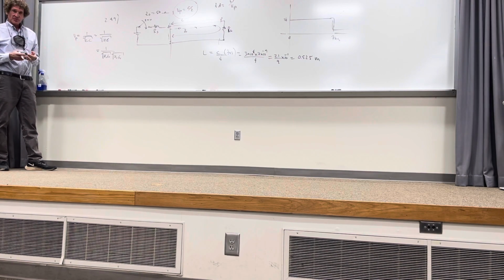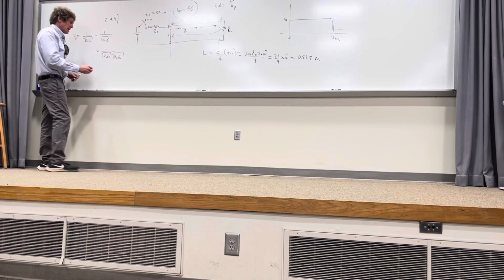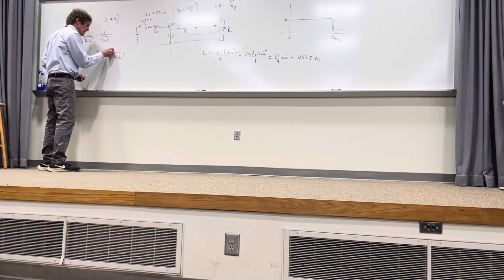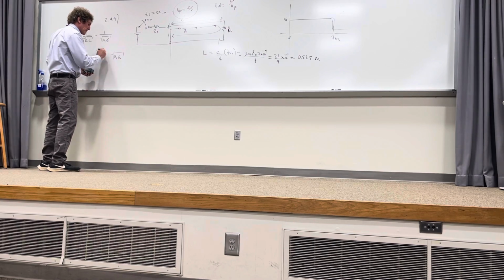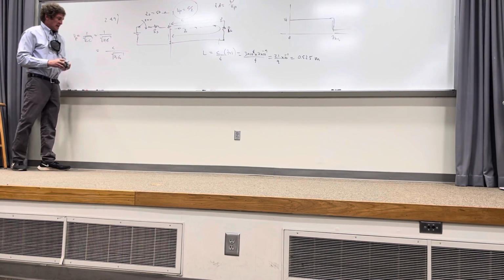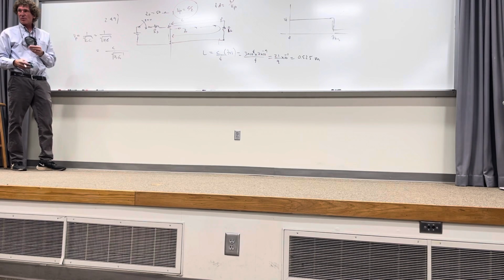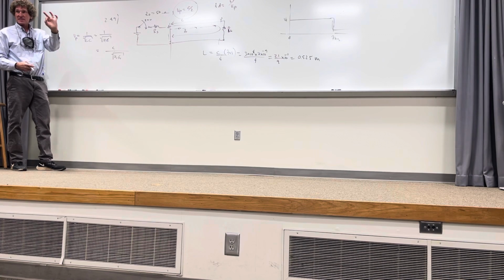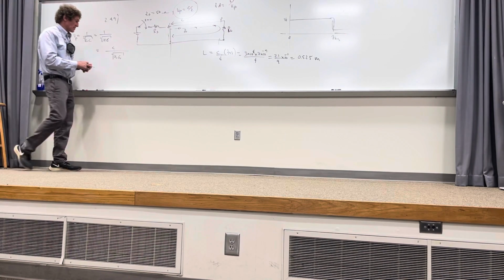Now, here's the truth. 1 over the square root of mu naught epsilon naught is what? It's the velocity of light, it's C, correct class? That's the fundamental definition. I'm going to replace this by C, right? Now, mu relative is called the permeability. It's always 1 for non-magnetic materials. It can only change if the material is magnetic, and there's nothing magnetic about the dielectric insulators. Do you all follow me on that? So we'll make that 1.